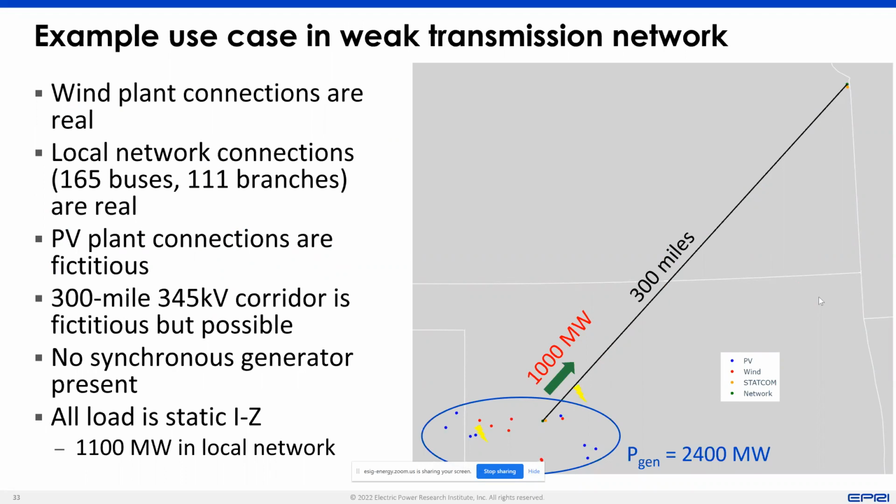If you have only load here, and all your voltage control only at this point, these inverters are going to be controlling voltage only based upon local information. If you're going to ship power here and have nothing to control voltage here, then the voltage can fall. So it's not about either or; you have to put it on both sides, because otherwise you'll have nothing to control voltage on this end.